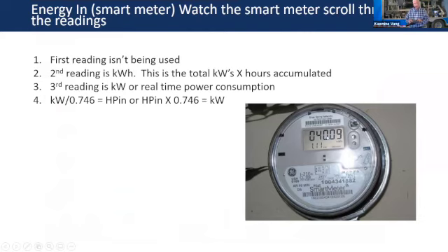We don't need to show it right now, but that's the other thing. So we're getting flow rate and total dynamic head off of our pressure gauges times 2.3, and we're getting energy in through the smart meter, and actually through our VFD. So that's one of the advantages. So we can do continuous pump efficiency. And with the VFD, we can show how that's being affected too, because VFDs don't necessarily make pumps more efficient. They just mean they can use less energy when you don't have to run them full speed. And that's the whole point of a VFD.